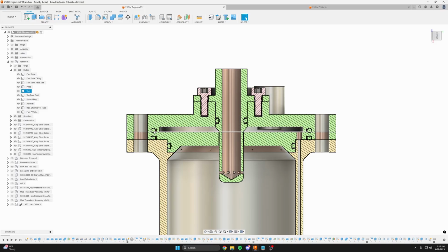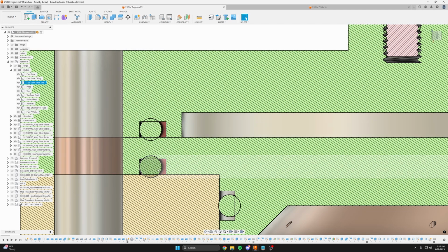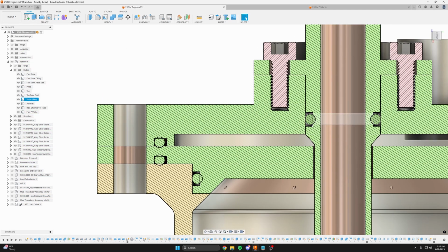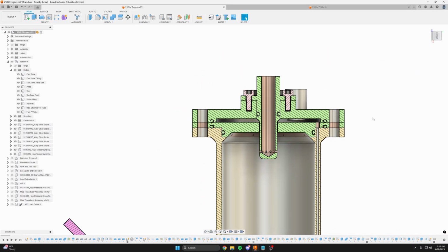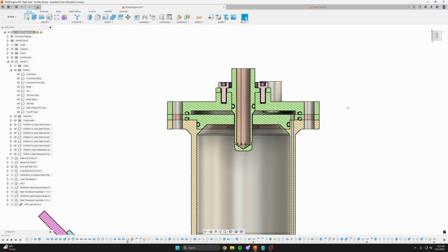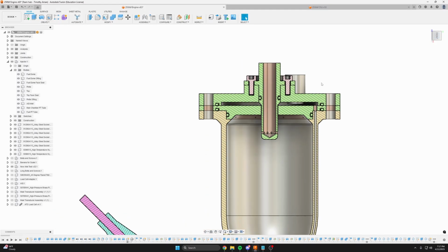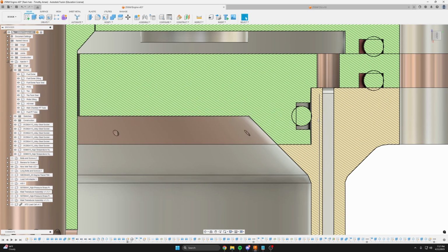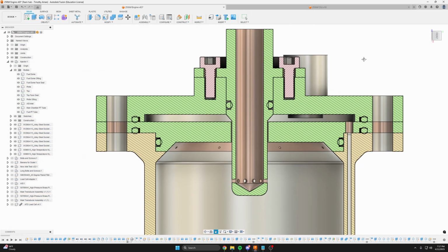And then obviously face seals are easier too, because you're just pressing up against it, and the O-ring will take up a lot of the slack if you have slight deviations in your machining. But yeah, I'll link the Parker O-ring handbook. That was pretty helpful to me when designing this.